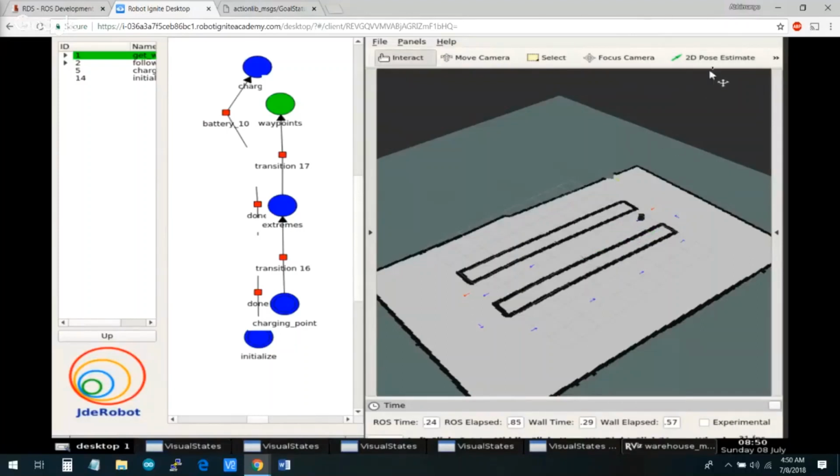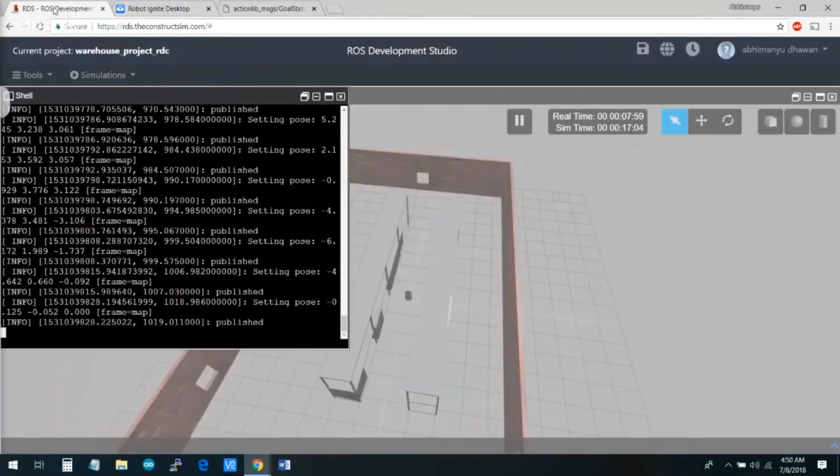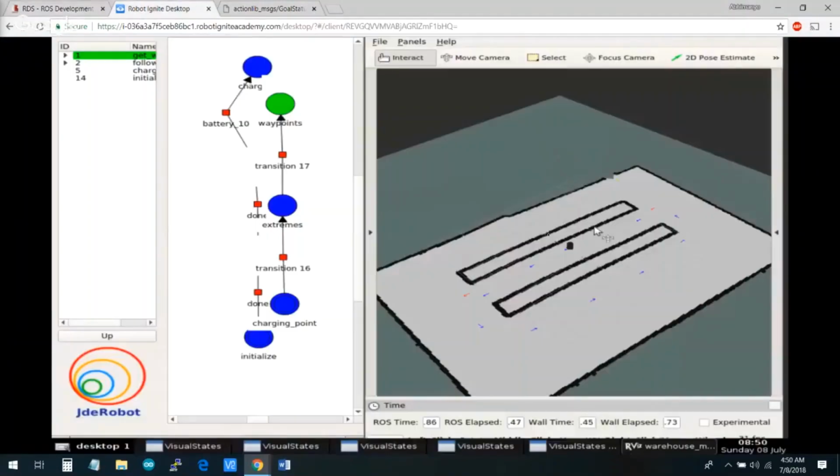So we are almost there. We just need to put the last waypoint, and this last waypoint you should put as the actual location of the robot, because 2D pose estimate tool is also used by AMCL. If you remember that, AMCL basically gets the initial pose using the 2D pose estimate, and we always want it to start from this location, right? So this is the whole trajectory that we defined for this robot.